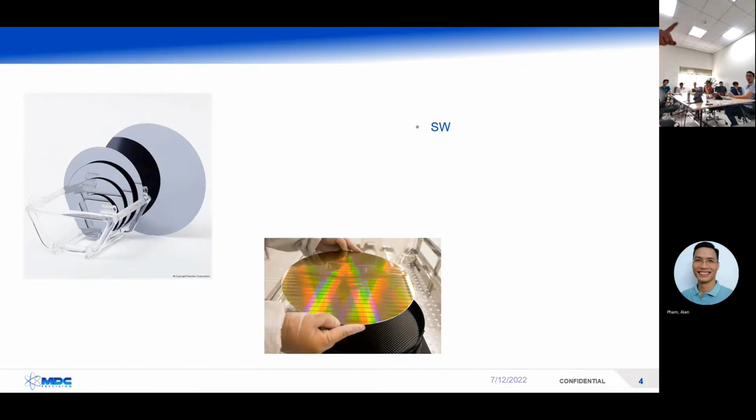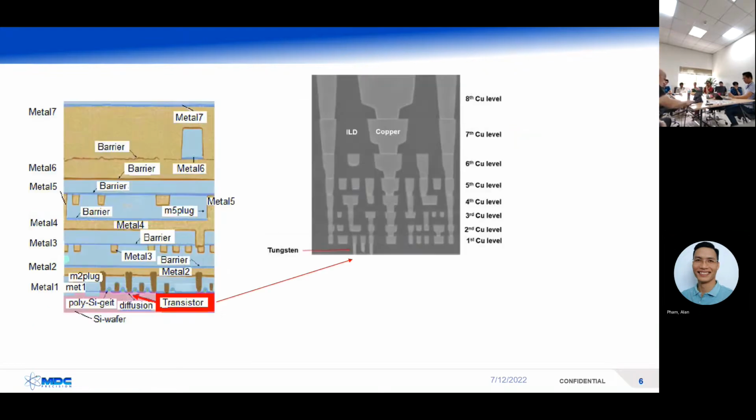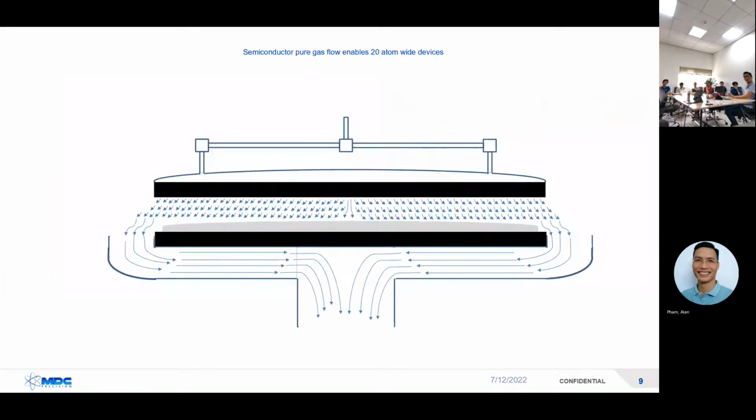The way to make a lot of them is just on a wafer. And of course, this is just how the design works. But in the end, it comes down to doing the layers. Remember, like I said, there's a layer where we etch, then it goes into another machine that does the same thing but with different chemistry and setup, and it takes off the mask. Then it goes to another machine to clean, then to another machine that deposits the conducting layer. So when you hear Lam Research, we'll talk about etching and deposition.